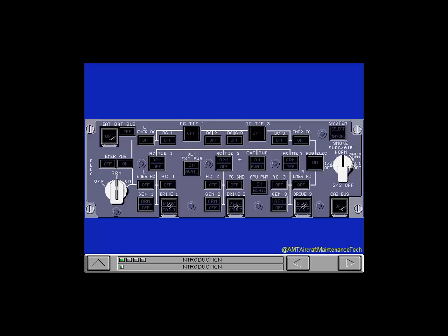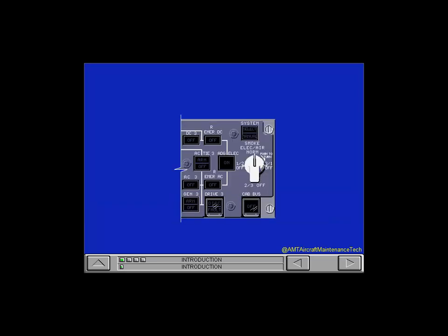There is one other time that a light on the system switch will come on. The manual light on the system switch will come on and flash if you try to use a switch light on the panel that the system controls in the automatic mode. There are 8 switch lights on the panel that will cause the manual light to flash. These lights are the generator switch lights, the 3 AC bus tie switch lights, and the 2 DC tie switch lights in the DC electrical system. Look at the generator 3 switch light as an example.